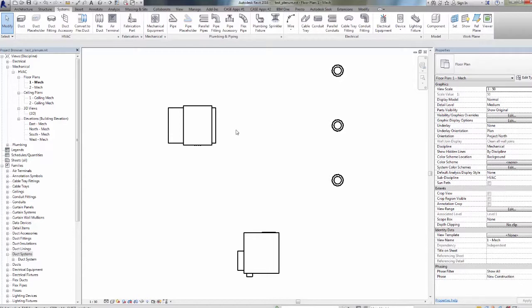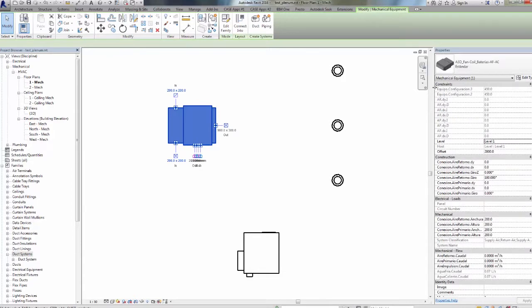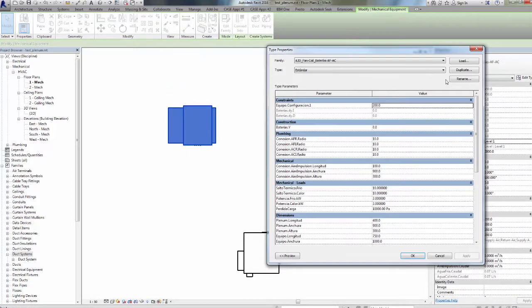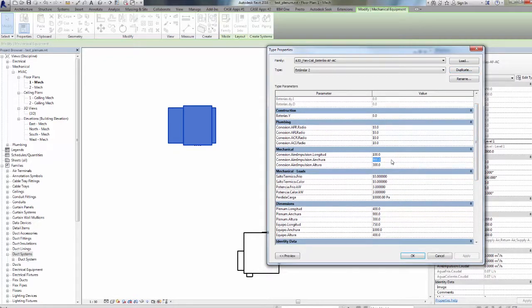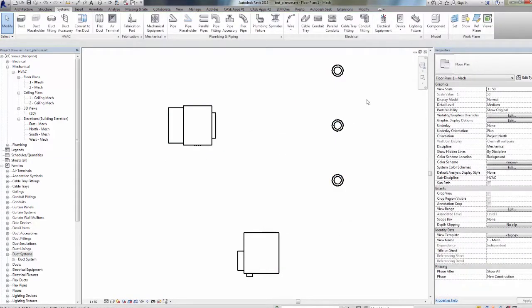The plenum will be selected according to the Airzone guidelines, choosing the model that corresponds to the HVAC unit which it's being connected to, and the number of zones. In this case we are considering 3 zones, and we are using a generic indoor unit instead of a compatible one. This way will also be useful in order to see what happens when the dimensions are not the exact ones. We are making a little change here and modifying its connections to see what happens when the connection is not the exactly correct one.